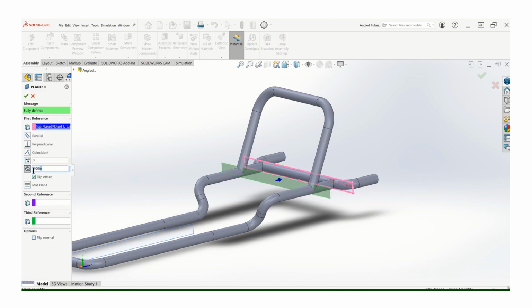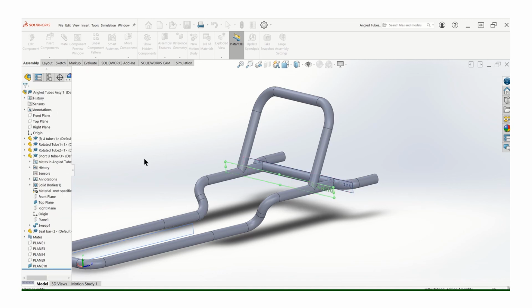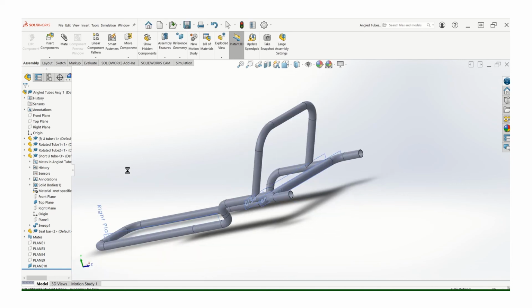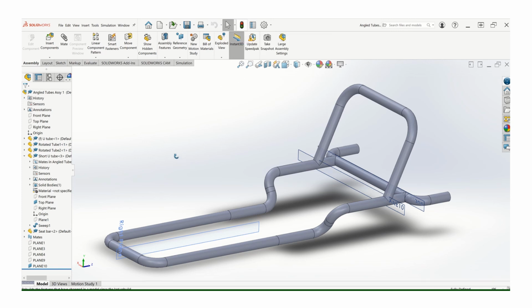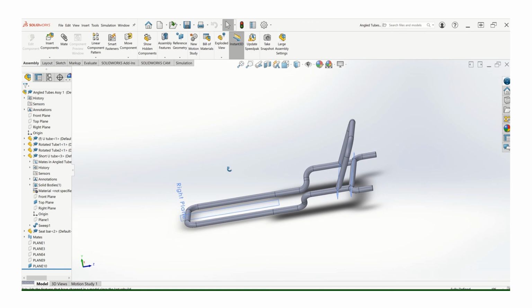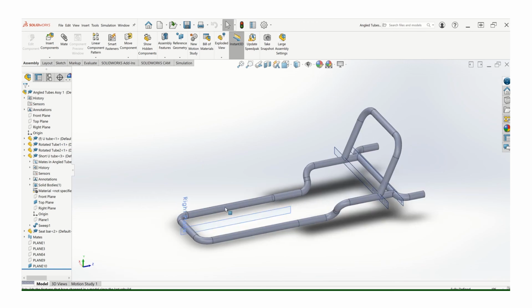Now I decide, nope, I want that to be 5 inches, just 5. The plane will shift. The part that's mated to it will shift with it. Now, if you have to force an update, just come over here and click on that. It should do it automatically. So that's easy to edit. Everything so far, I could change every single piece of this pretty easily by using parametrics.